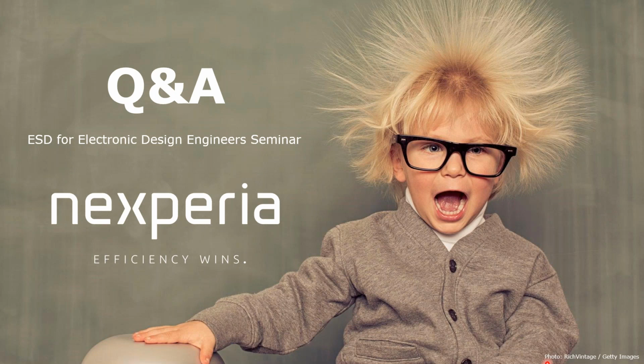Usually in data sheets, you find a statement which current is the threshold to define the breakdown voltage. It's usually 10 milliamp. And the reverse working maximum is where the device has a very, very low leakage current of a nanoamp or something like this. So this is basically the difference. And this is also the reason why there's always a gap between the reverse working voltage and the breakdown voltage. So if you think of a simple Zener diode, it's the difference between 1 nanoamp and 10 milliamps.